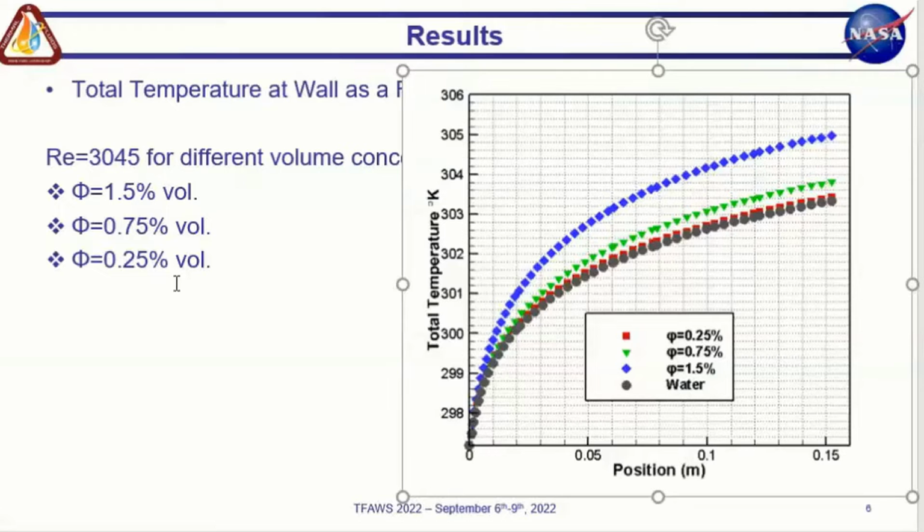Okay, thank you. And got still a couple more. It looks like you used the metric of fluid surface temperature for enhancement of heat transfer. Did you consider the use of bulk fluid temperature for the metric of heat transfer enhancement? From a practical perspective, have you considered what would be the more appropriate metric given that the conductivity is increased by about 4% from quarter percent to 1.5% volume fraction?